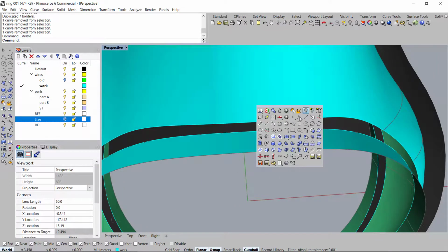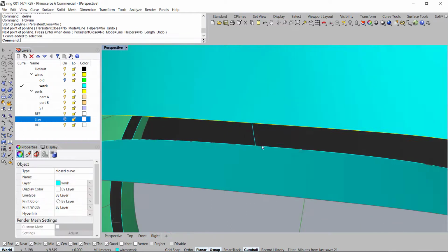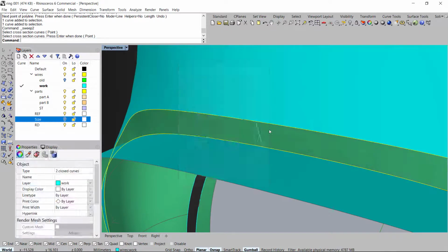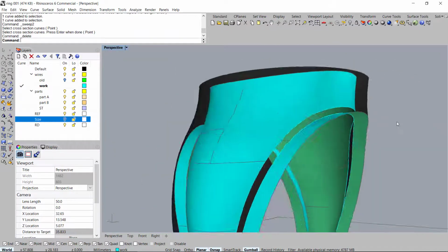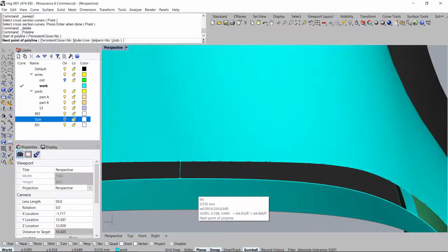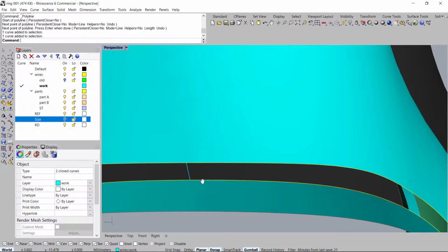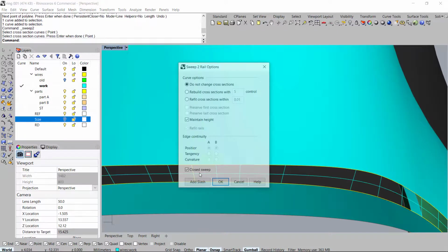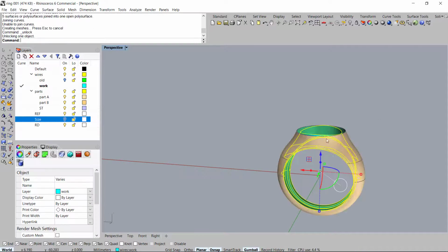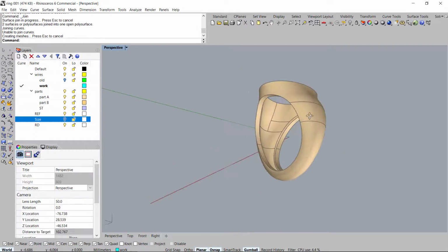Let's try sweep 2 rail. So just create a cross-section line going across. Apply 2 rail sweep. Just join it. Looks like it worked. Do the same on the other side. I don't trust mirroring it because you never know if your surface is wrong on the other side. I'm just taking that chance, you know what I mean? There you go. So go ahead and just join it. Unlock our scene. Go ahead and just join everything. Alright, so this part is done.